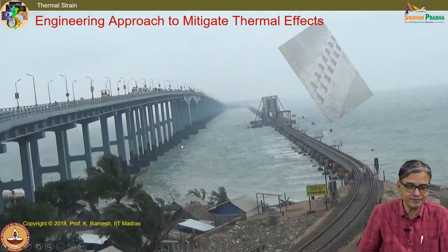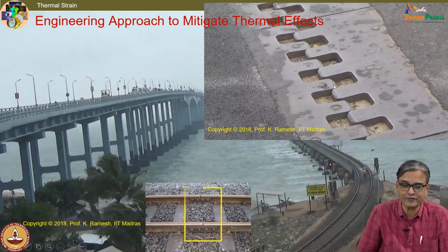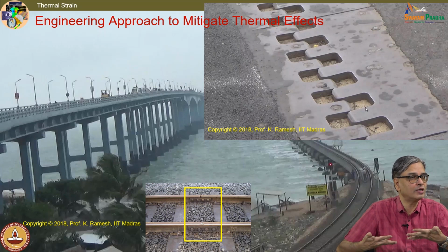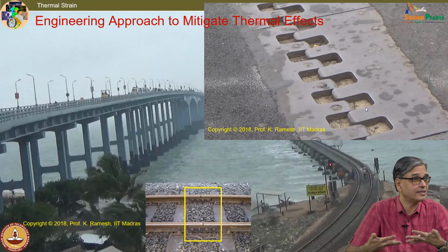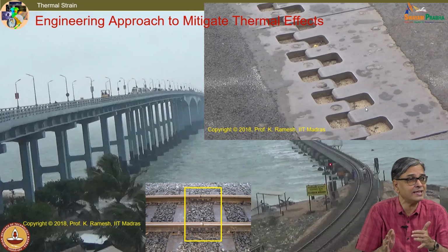And I was surprised when I visited that place, the road bridge has this kind of features. So, you have interlocking steel plates that come in and go that accommodate the temperature change. It is very interesting, people have accommodated the thermal effects in the design so that you minimize the additional load due to thermal stress.